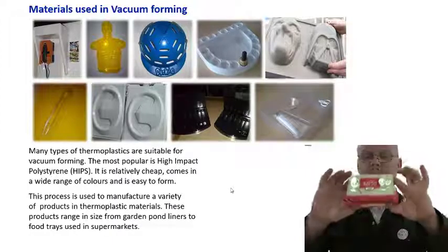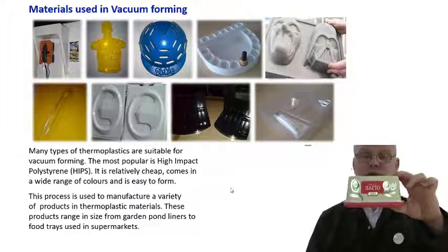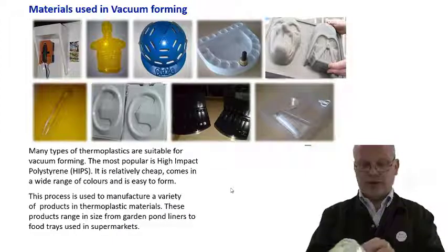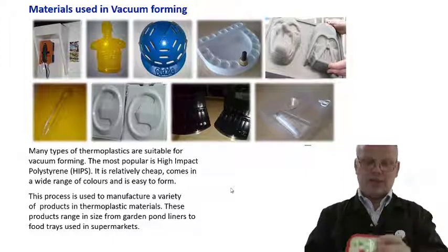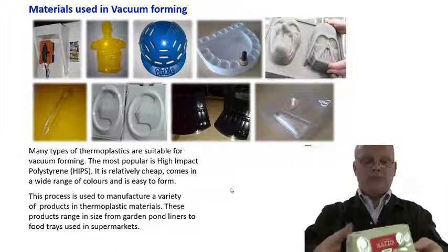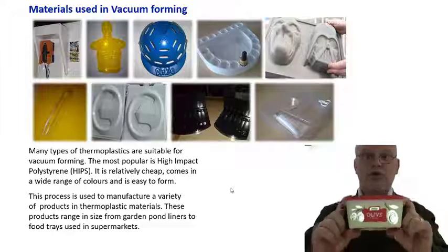Okay, so vacuum forming, suitable for small scale production, but obviously this is going to be a mass produced product as well, so it's suitable for different scales. This material, I'm just going to see if on the packet I can see it, probably something like polystyrene, and it's got a very thin wall, very flexible, so really good, mass produced, relatively low cost.